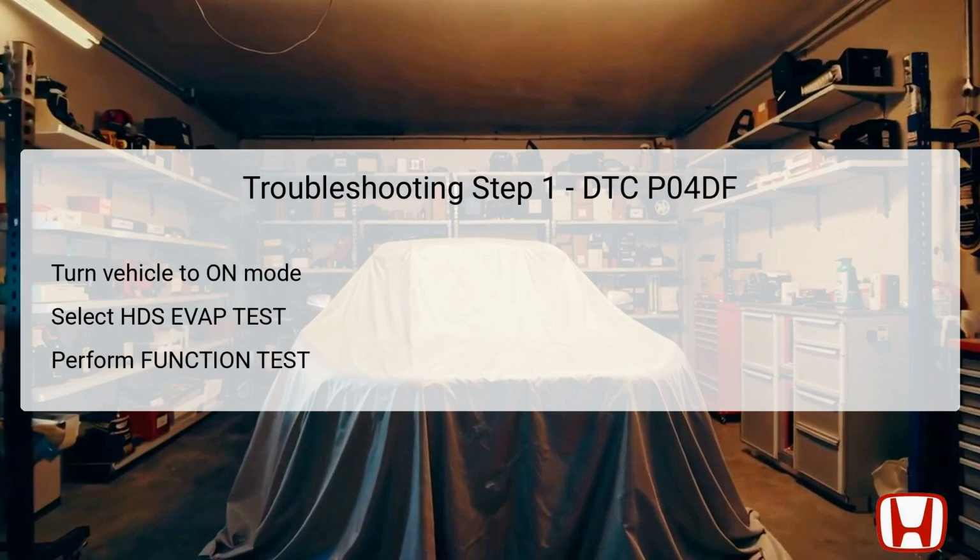The first step in troubleshooting the P04DF code is to ensure the vehicle is in the proper diagnostic mode. Begin by turning the vehicle's ignition to the on position without starting the engine. This prepares the vehicle's systems for diagnostic testing. Next, select the Honda Diagnostic System, HDS, and navigate to the EVAP test option. This step allows for a targeted assessment of the EVAP components.